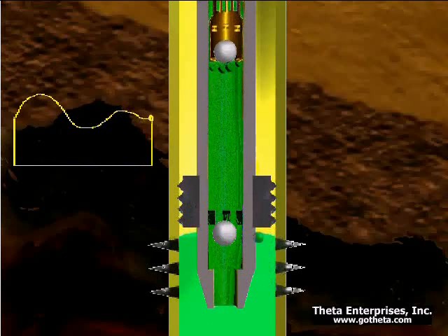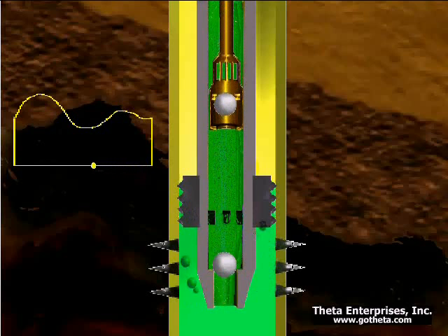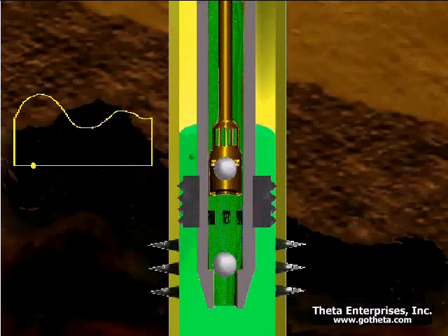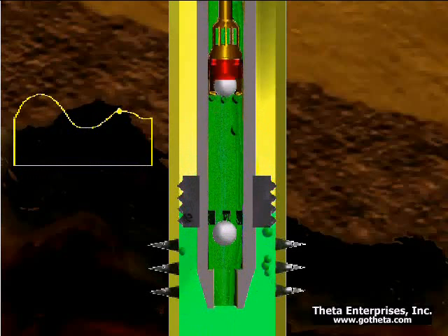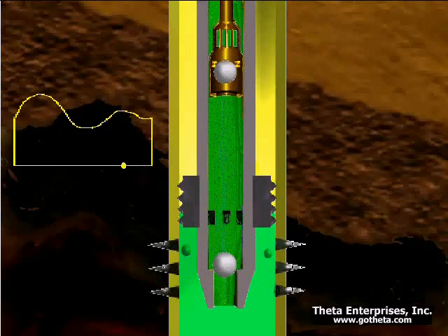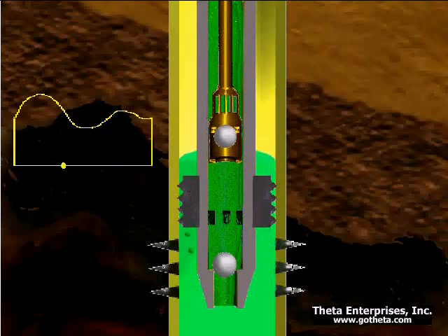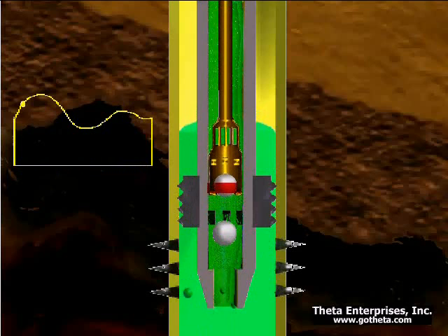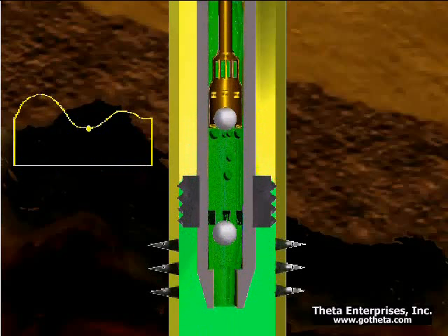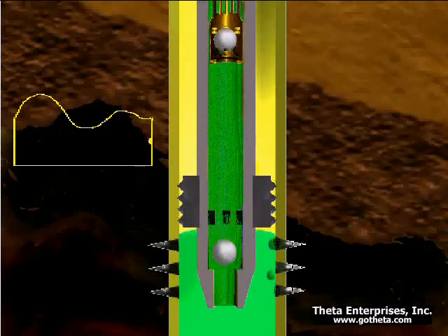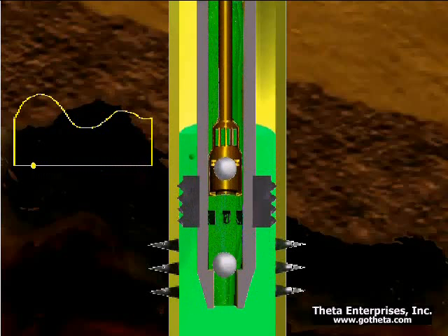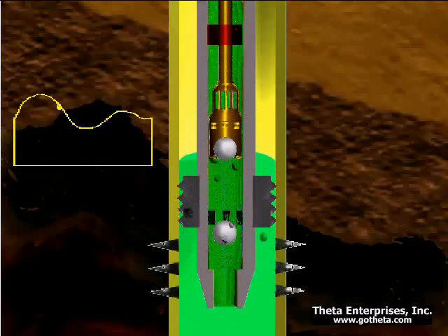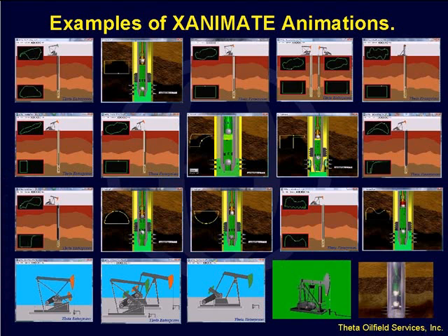That is the pressure wave that travels through the fluid, hits the surface, comes back down, and gives you a reflection right there, which causes the load to go back up on the plunger, but not as much as before. Those of you that don't have these types of wells probably have not seen this before, but we have a lot of shallow high rate wells outside of Bakersfield that do this exact thing, and in other parts of the country as well.